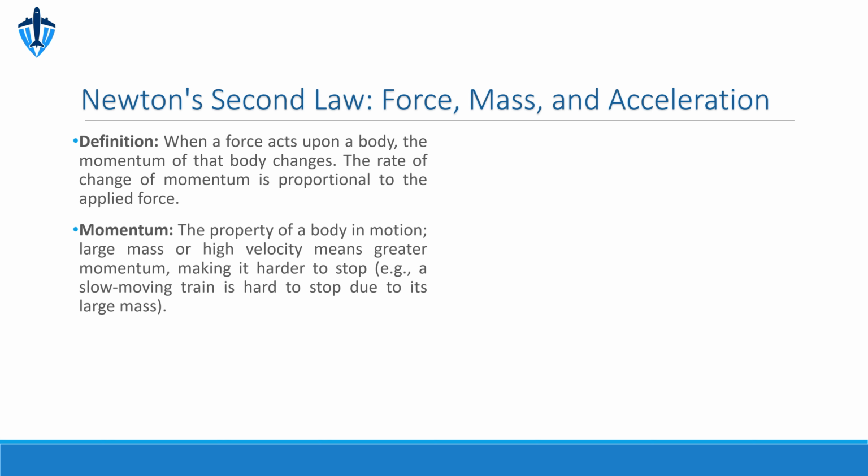Now, let's explore the fundamentals of pulleys. At its core, a pulley is a simple machine, characterized by a grooved wheel, often referred to as a sheave, which is mounted on a fixed axis and supported by a frame known as a block. The primary purpose of pulleys is to assist in lifting or moving objects by either changing the direction of the force applied or by magnifying that force. When we combine a pair of these blocks, each housing one or more pulleys and connected by a rope, we form what is known as a block and tackle system.